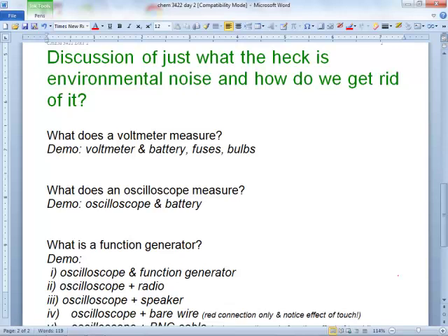So with the bulb, the trick is just knowing where the wire's connected. One wire's connected to the very center. Where's the other one? Yeah, this guy. So you connect him. It doesn't matter which probe goes where. Then the other one to the end. Is this bulb good? Yeah? Okay, so this bulb's good.